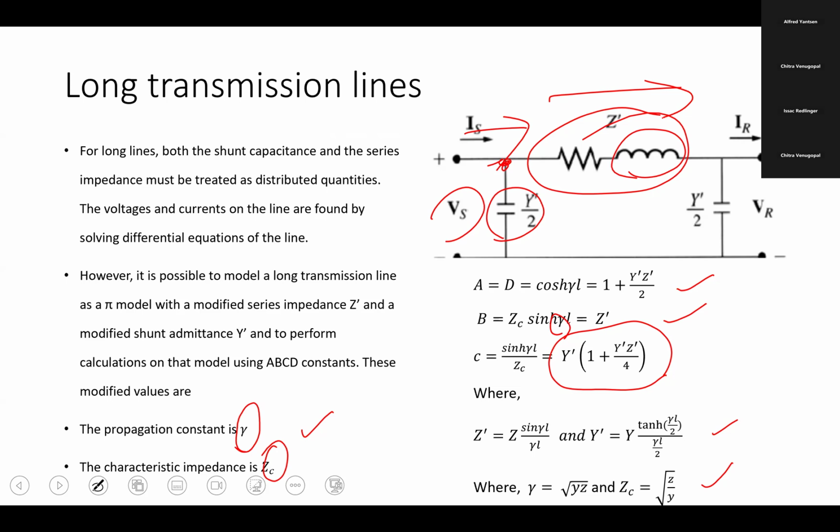If both are running at a similar speed, not the same speed, they cannot run at the same speed because there is inductance in the line which can store current, so it makes the current lag behind the voltage. They have to reach the destination not at the same time, but after a certain time. Like if, say, a 3 microsecond delay: the current is running 3 microseconds delayed with respect to the voltage.